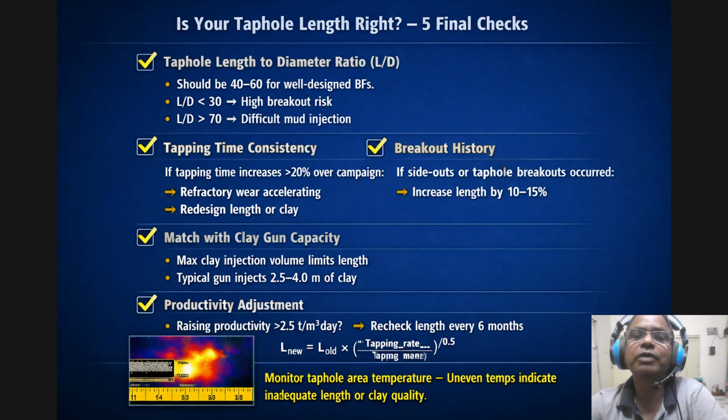Finally, always monitor the taphole area temperature with thermal cameras. Uneven temperature means poor length or bad clay quality.